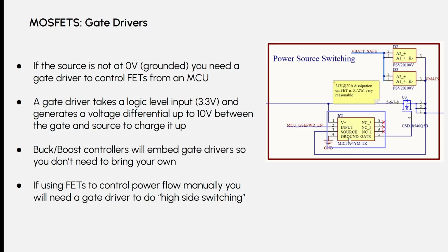the solution is a gate driver, and a gate driver does exactly that. It generates a voltage difference, usually at least 10 volts, between the gate and the source, and you can control it using a regular 3.3 volt signal, which is very convenient, very good. I will say, if you can avoid it, definitely avoid doing this. Gate drivers are kind of expensive. So really what you do is you get a load switch, and a load switch is just an integrated circuit that has both of these things together in the same chip, like a MOSFET and a high side gate driver.